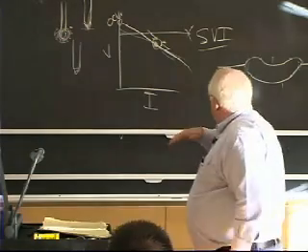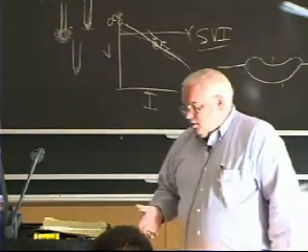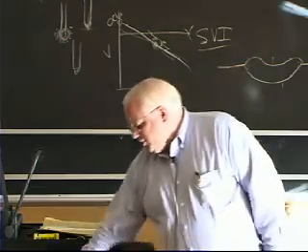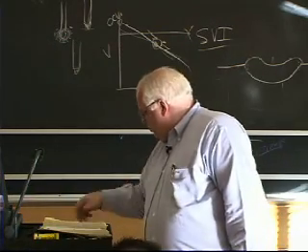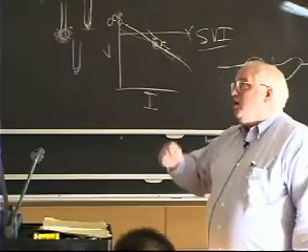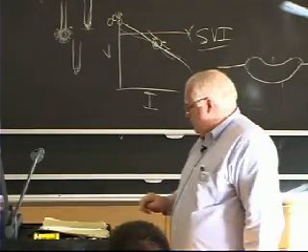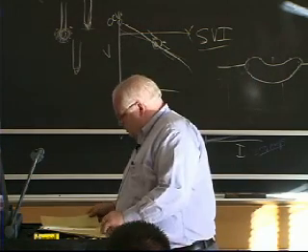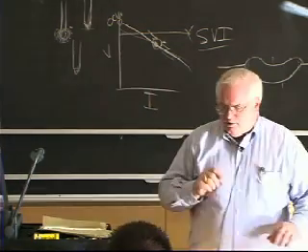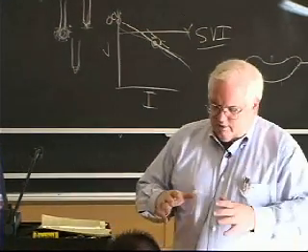So the arc pressure depresses the surface of the weld pool, which can lead to all kinds of deformation of the weld pool and defect formation. It also allows us to weld out of position. It pushes the drops up against things. What else does it do? Oh, it contributes to arc stiffness and prevents arc blow.